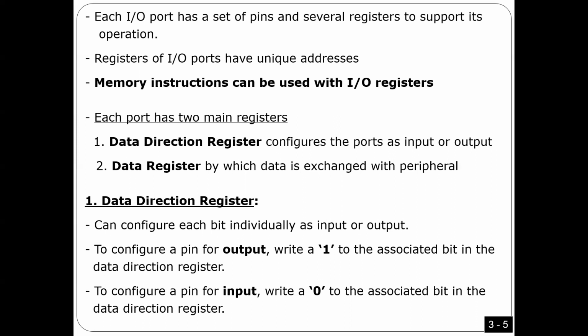So you have a register with an address number, and if it is output, you write logic 0 in this byte so that you put 0 volt here, or logic 1 to put 5 volt here. This is if it is output. If it is input, it's going to be a little bit different.